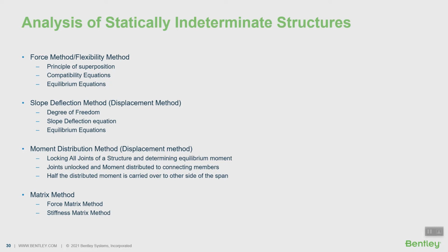So far, we have discussed the analysis of a statically determinate truss structure where the equilibrium equations were sufficient. But majority of the structures today, which are designed in modern engineering, are statically indeterminate. This is mainly due to added members and supports, and also due to general form of the structure. Reinforced concrete buildings, for example, are nearly always indeterminate, because the beams and columns are casted as continuous members through the joints and over the supports.